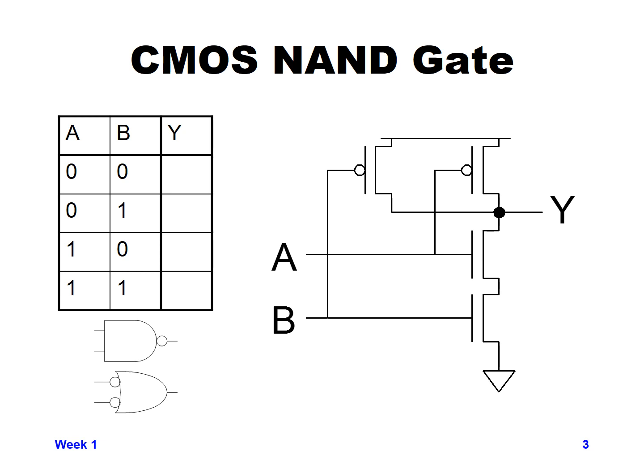The uppermost of the 2 symbols is an AND gate, the basically flat line on the left side and the curve on the right is how an AND gate looks, but with the bubble on the output, it's an inverted AND gate, which is called a NAND function, not AND. So the NAND gate there is the upper one. The lower one is an OR gate, but with bubbles on the input. So it's doing an inverse of each of the A and B inputs, and then doing an OR of that function.